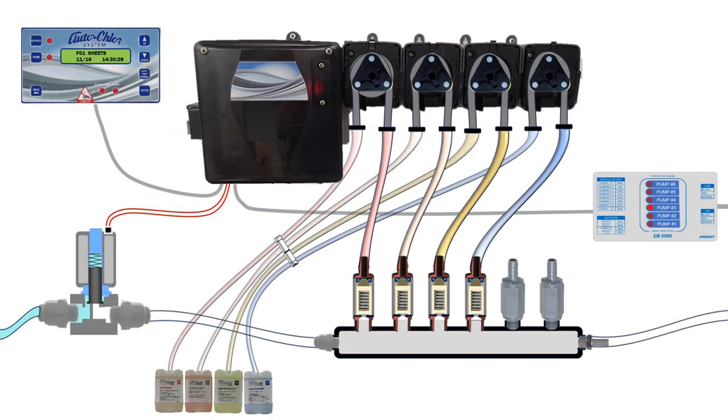This signal is transferred to the dispenser, and the corresponding pump, based on its programming, will dispense the bleach. As the bleach enters into the manifold, the flush solenoid will turn on and flush the bleach into the washer machine. When the chemical has stopped pumping, the flush solenoid will continue to flush the line clear.